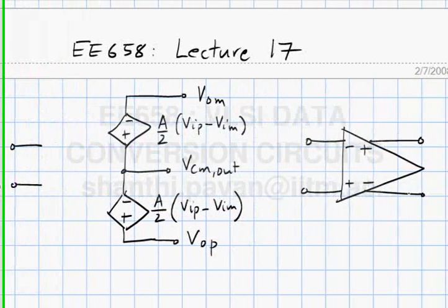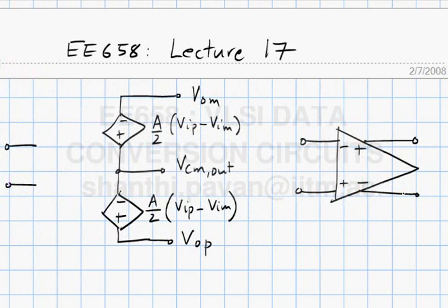You put another common source amplifier in cascade, and then you realize that when you close a loop of this nature, the quality factor of the closed loop system will be very, very high, okay? And the poles will be dangerously close to the j omega axis. So to fix this problem, what will you do? You put a dominant pole and make it look like a first order system, and this is all the same old that we have seen over and over again.